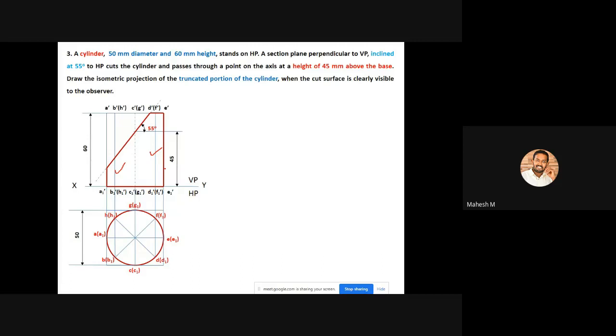So our condition is that we have to project the cutting points towards your top view. Here there are no slant edges and no longer edges, so you can directly project this particular point towards your top view, because some of the top surface has been removed.